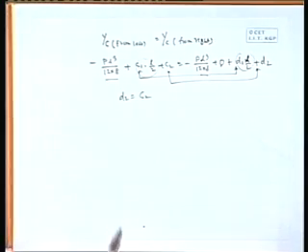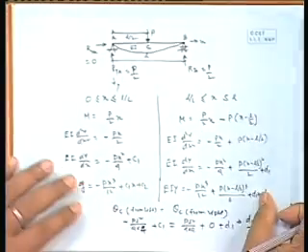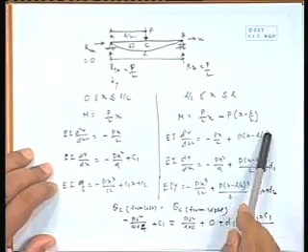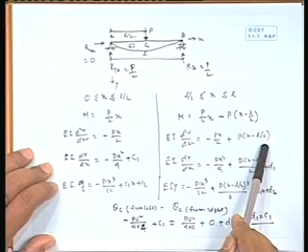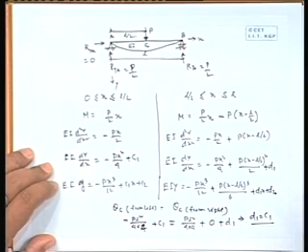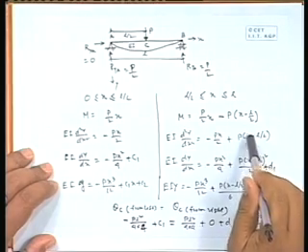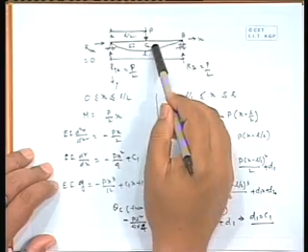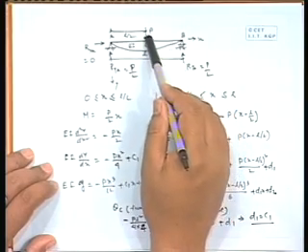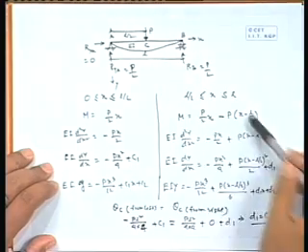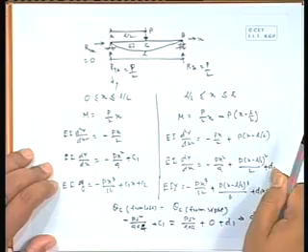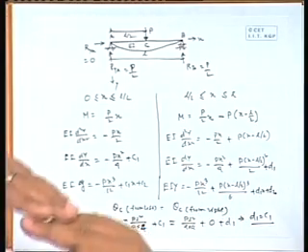The main reason is, I shall show you again the previous page, the additional term x minus L by 2, this term applies after L by 2, but at L by 2 exactly the value is 0. Okay. This load will give some moment on the right side, but it will start from 0 value. Okay. So when we are putting the boundary condition, that part is becoming 0, whatever additional term we are getting. Okay. So ultimately it is becoming an identical constant within the equation.